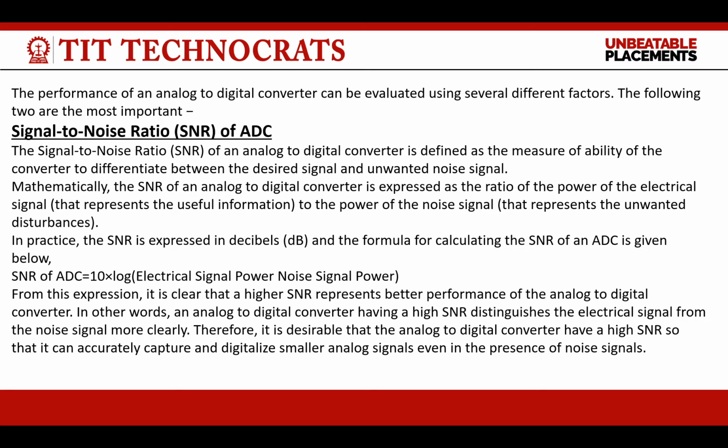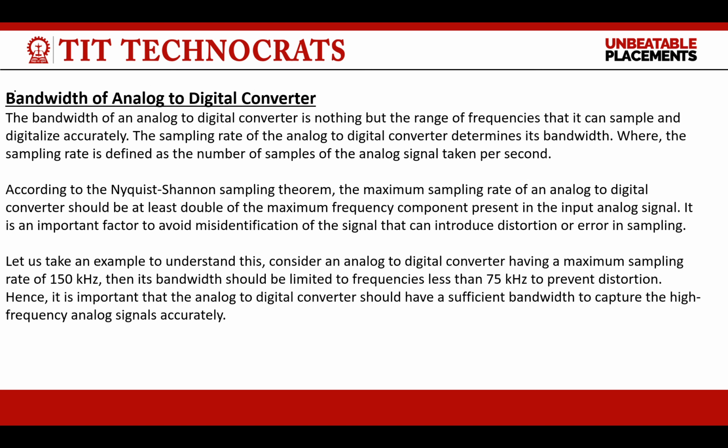Therefore, it is desirable that the analog to digital converter have a high SNR so that it can accurately capture and digitize smaller analog signals even in the presence of noise signal. So SNR is the ratio of 10 log electrical signal power to the noise signal power.